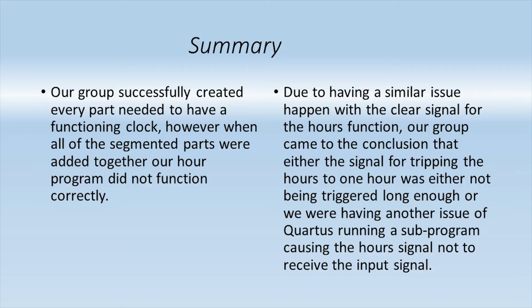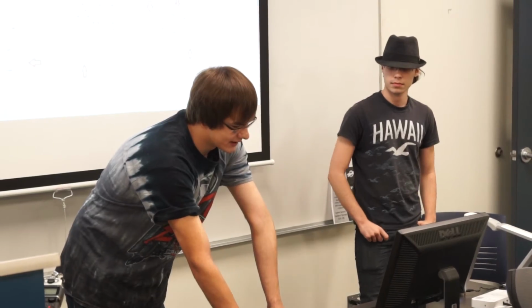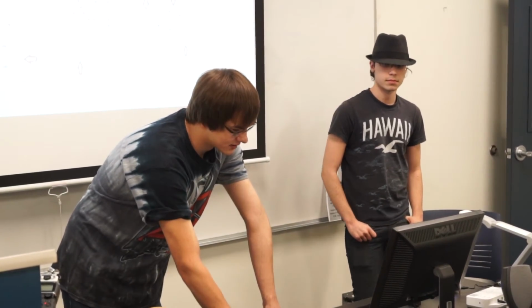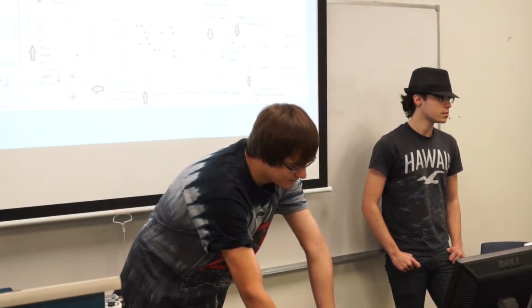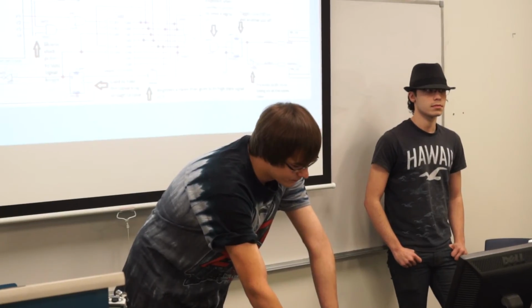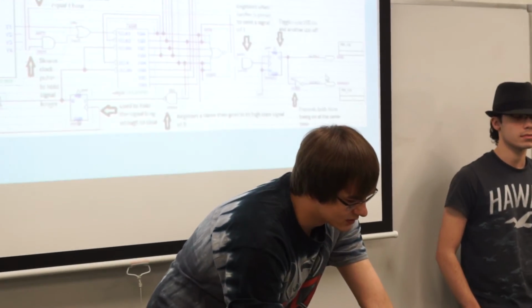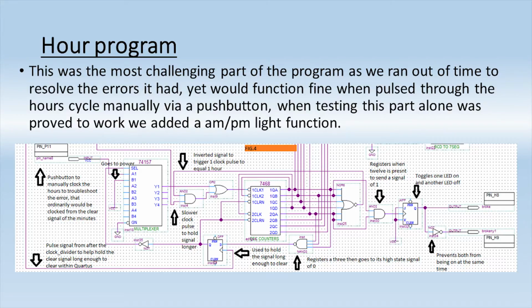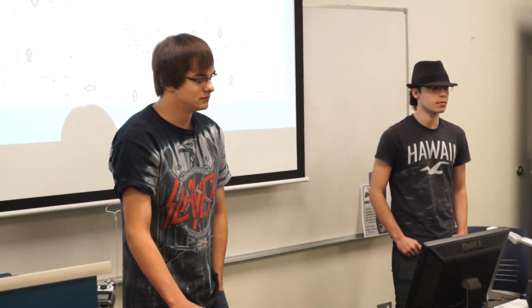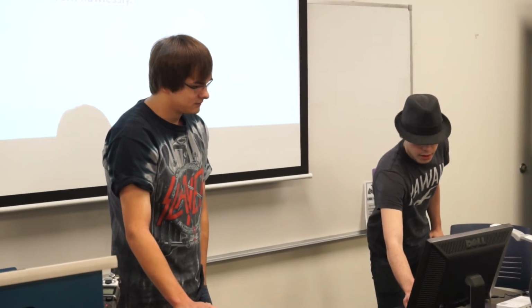And going from there, one thing that was very trivial that just has to come with the standard clock is our AM/PM switch. It comes from a JK flip-flop, which is always in toggle mode. So one of these is the AM or PM. You just have to designate one, but every 12-hour cycle it'll toggle to this or toggle to this. So that lets you know if it's 2 p.m. or 2 a.m.